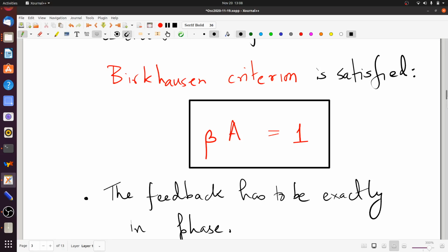This is because electrons inside the components execute random motions. So there's always electrical noise, which is a tiny random signal of all possible frequencies floating around inside the circuit. Basically, it's this electrical noise that provides the input to this circuit so that the oscillations can happen.